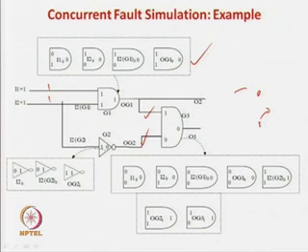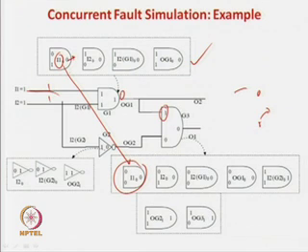So, you can see here the answer is a 1, correct, but now if this stuck at 1 fault is 0, so this gate output will be a 0. So, here you are going to get a 0 and the answer is 0. So, this one you have to keep. So, how are we deriving this? We are deriving this from here. That is, with any signal change, if this signal change is from 1 to 0, then you have to put it. Now, how do you know that this will be changing? This is the fault I1 stuck at 0, this stuck at 0 will result in a 0 at this gate output. We can find this out from this bubble list. Okay. And then this 0 means the signal is changed. So, this one we can put it.